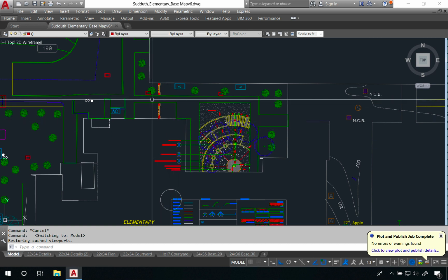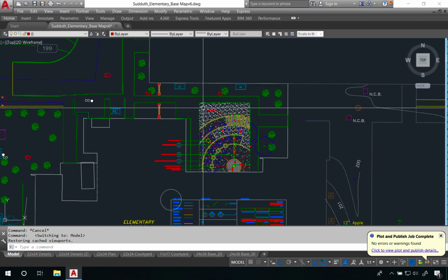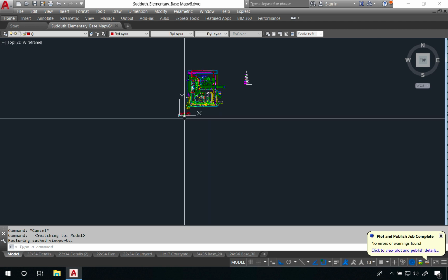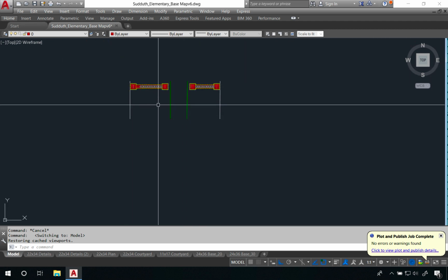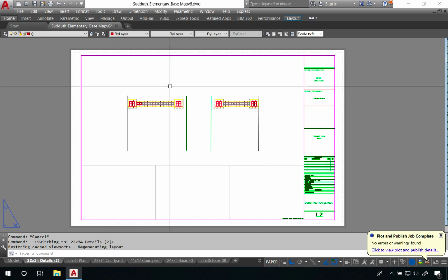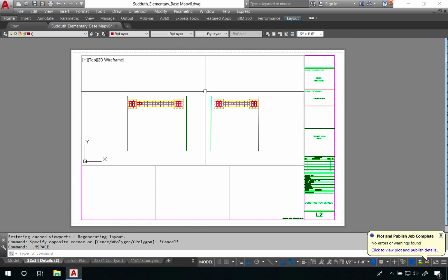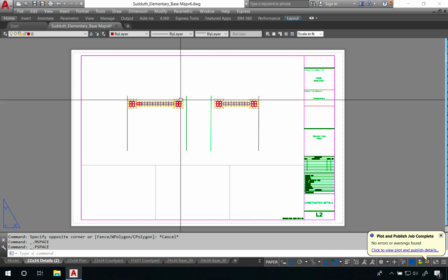Now, if we wanted to create this section entirely by hand, it would be helpful to take this particular part of the section, cut it out, rotate it, and place it in a different part of our drawing. This allows us to scale this particular piece. Right here we have it scaled to 1/2 inch equals a foot, and to print this out as a PDF and ultimately as a sheet of paper for us to use as the basis for our section elevation sketch. Once printed, we would know this is 1/2 inch equals a foot.